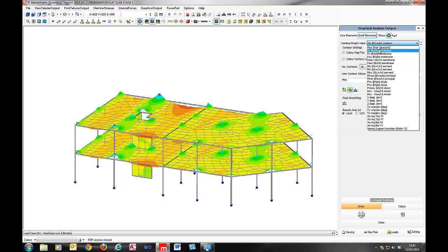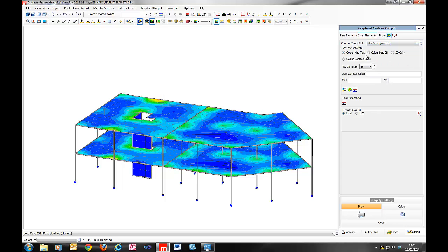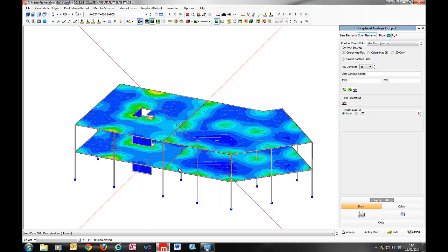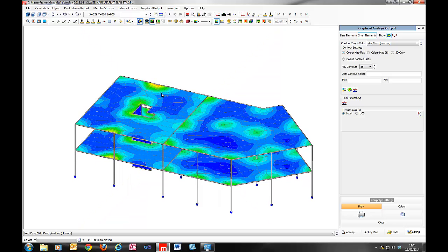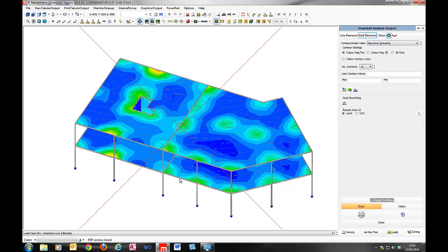Now, before I start looking at results and particular values of results, it's always a good idea to check your maximum percentage error. Now you might say, if you're maybe not that familiar with finite element analysis, well, why would there be an error? That is the nature of finite element analysis. If we perhaps don't have a refined enough mesh, a small enough mesh to capture the variability of the stresses which may be occurring, then the resulting analysis could be erroneous by a certain percentage.